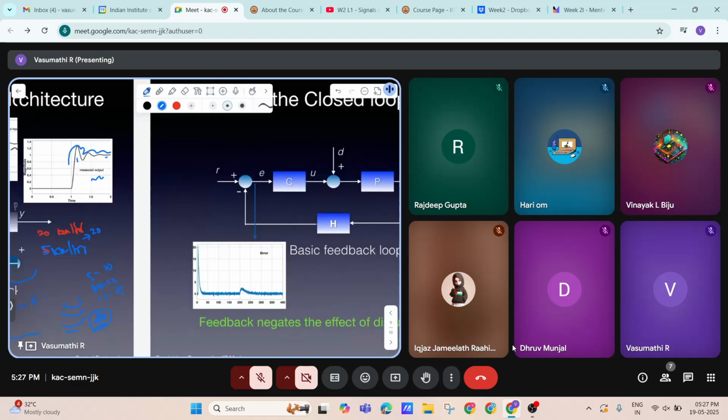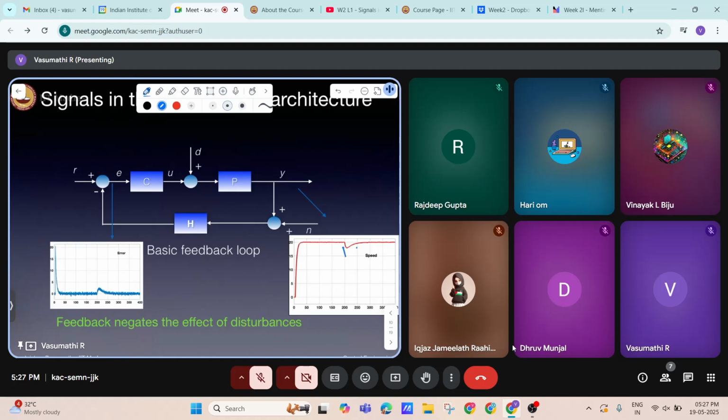Here you can see the time taken for the control action to apply. We gave an input of 1000 engine force, and we got a good output around 20. Some disturbance happens at this place, so there is a deviation. The value went down, and this time the control action was taken, so it is brought back to 20 kilometers per hour.